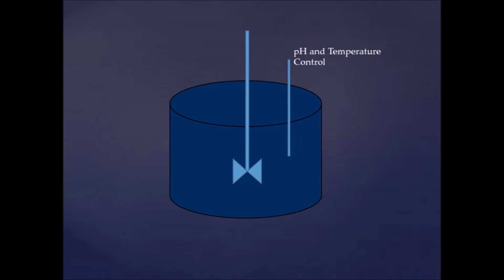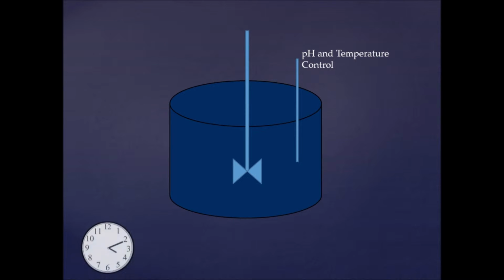The process is very simple and is similar for both methods. In a reactor, the product is introduced first. Then, lactase is introduced into the reactor, in order to react with the lactose. It is important to notice that there must be an agitator to provide a well-mixed medium. Also, temperature and pH are controlled during all the process. After a given amount of time, there is not much lactose left, so the product can now be removed.